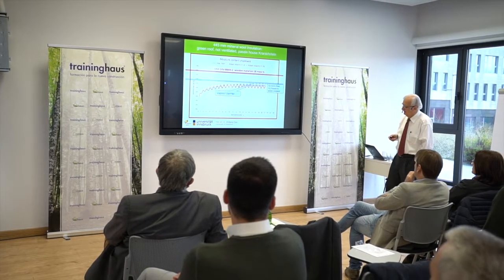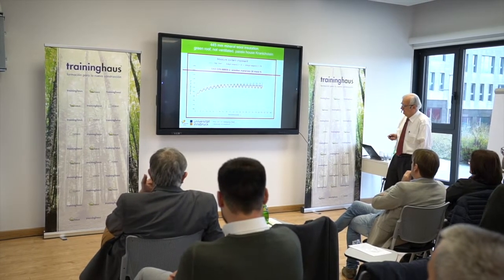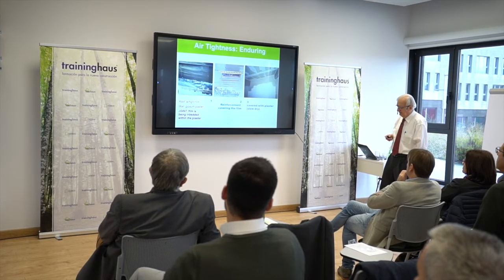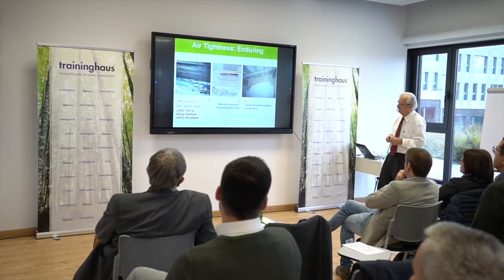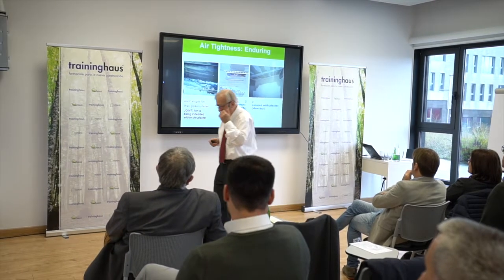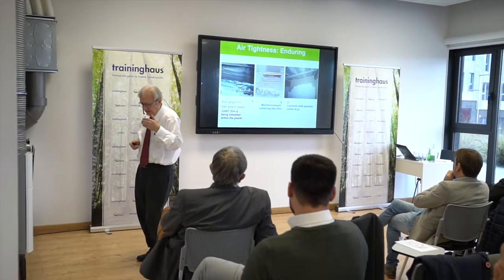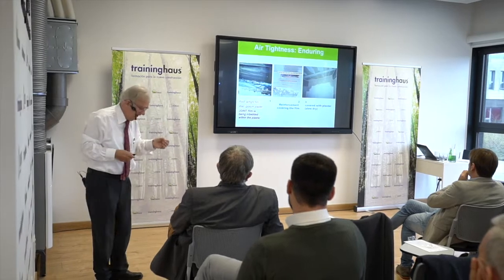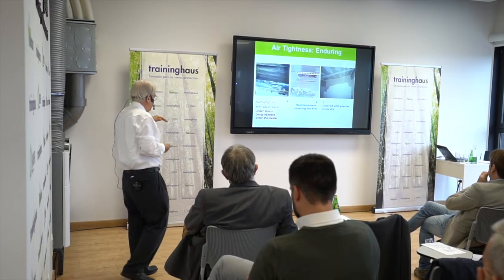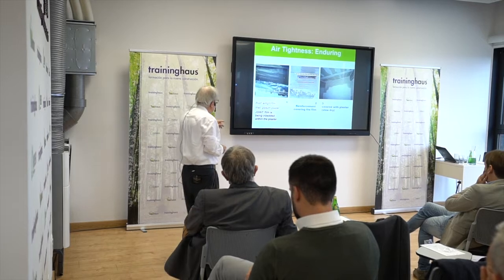But what I've shown you here, the most important thing in order to be able to do that, is to have it built really airtight. So now some hints about how that can be done in such a type of construction. If you have this combined timber roof construction and the wall plaster as an airtight layer, I've already shown that.